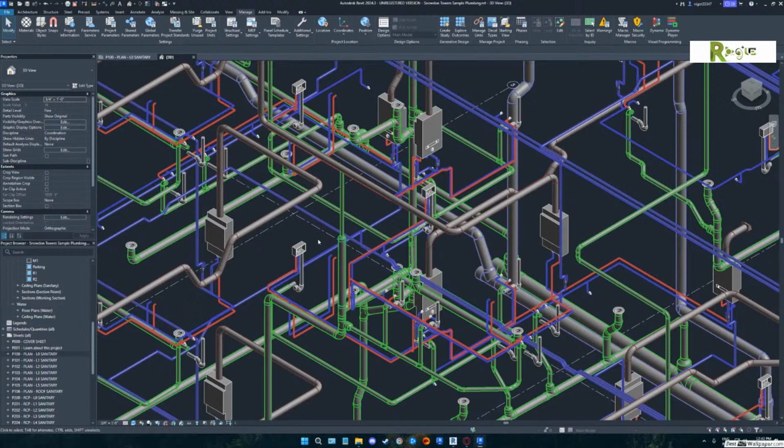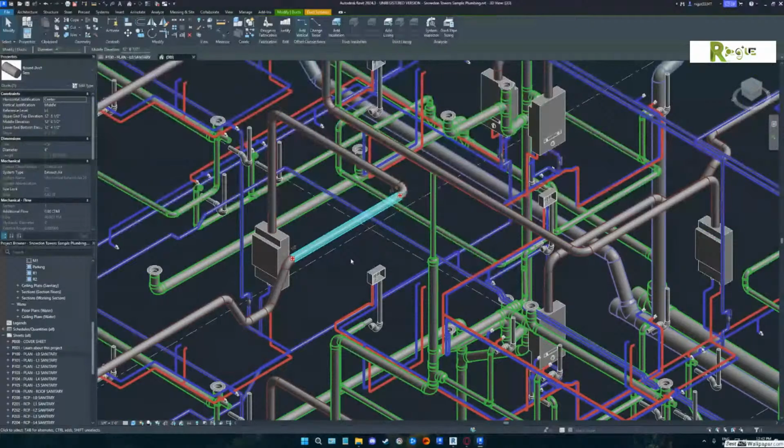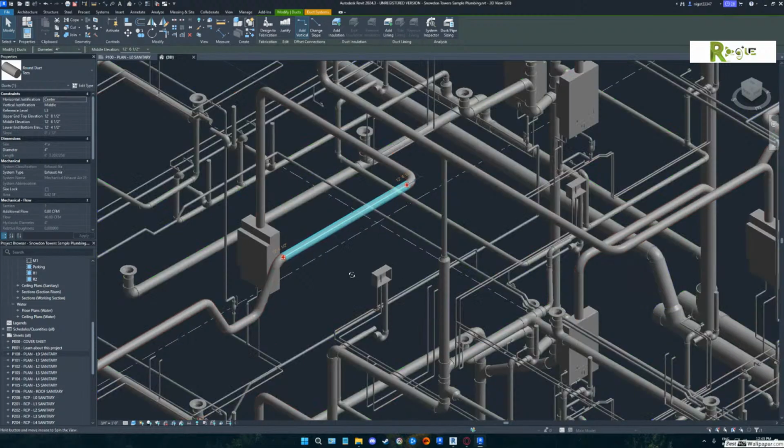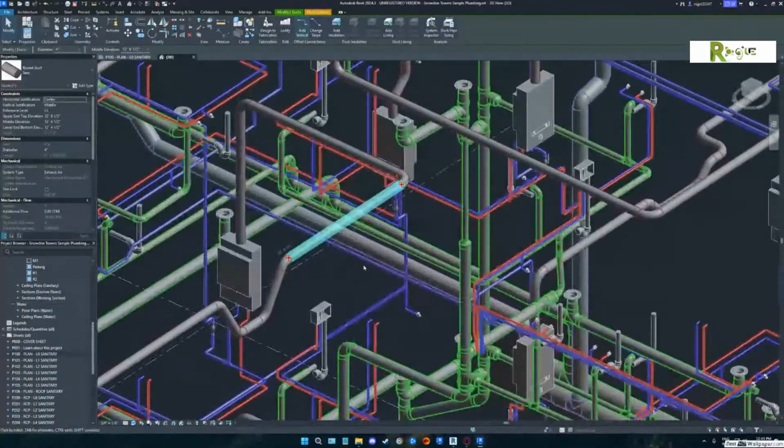If we picked on the brown pipe, we would find out that that's actually not pipe, it's duct. And it's called exhaust air. See that? Okay. So here's the funny part: it's so easy to change this setting. I don't know why they never did. So most people you're going to run into don't do this. So what we find is it's the system type of exhaust air.